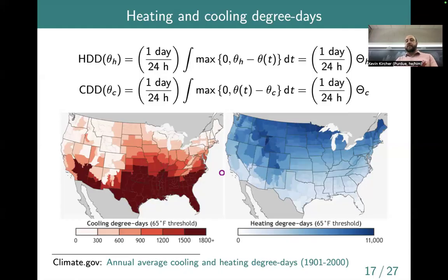Yeah, so the question for folks online is basically, how would we calculate heating degree days if we had specified that balanced temperature, say 65 Fahrenheit, and we knew the temperature today, the temperature yesterday, and so forth.